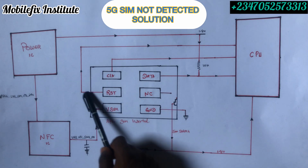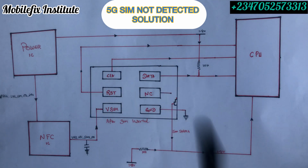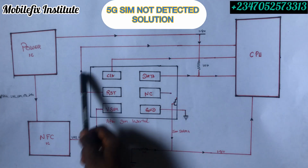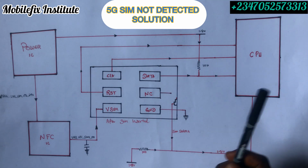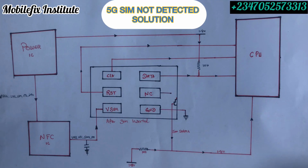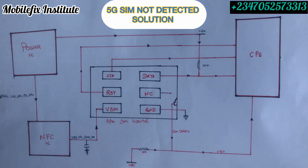Ensure that you follow this line using your schematics. So it is very, very important to understand how to trace your circuit using the schematic diagram. After connecting this line, you discover that your phone will now detect SIM. But in case there is no short circuit and no open circuit, you have your value. Now what can be the reason why your phone is still not detecting SIM?